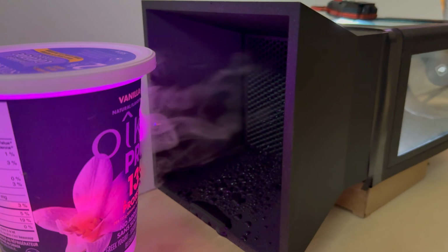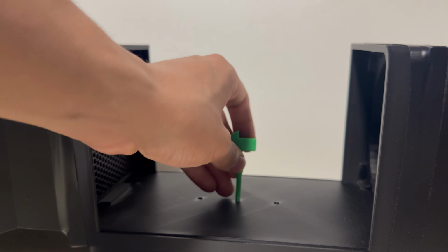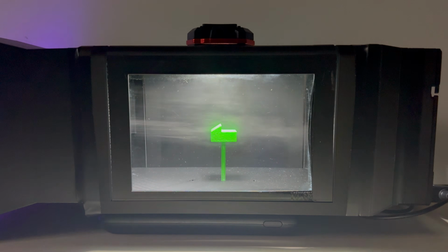The fan pulls air through the intake, and the mesh block breaks up the larger eddies, then the converging duct accelerates the flow towards the test section. Here you can see the mist threading through. As you can see, everything works. The flow looks reasonably laminar at mid-fan speeds, and you can put a small object in the test section and see streamlines deflect around it.